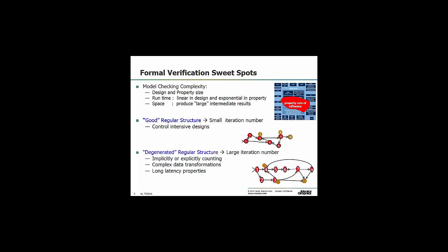For this kind of design, the FSM that you get from the synthesis has a very, very large diameter. This is why, as vendors, when we go to customers we tell them it is best suited for designs which are control intensive. It does not mean it cannot be applied to other kinds of designs, but you should expect that formal verification will spend more time and need more resources to be conclusive in that part.